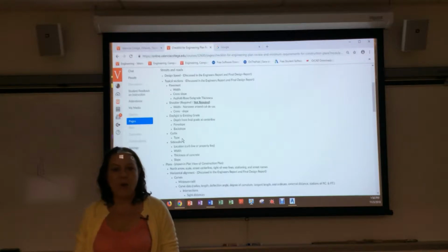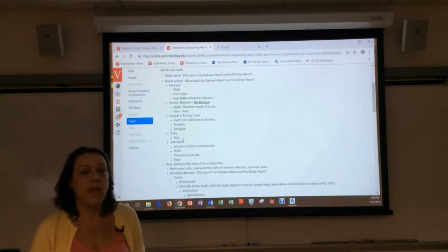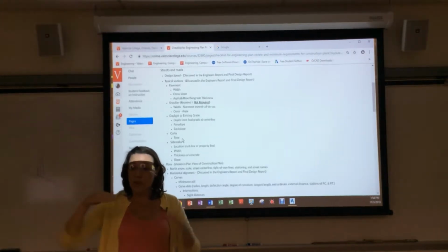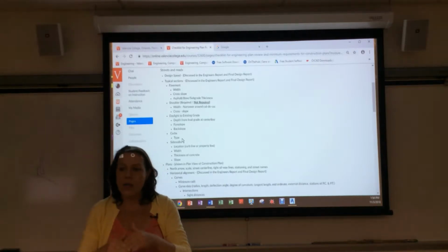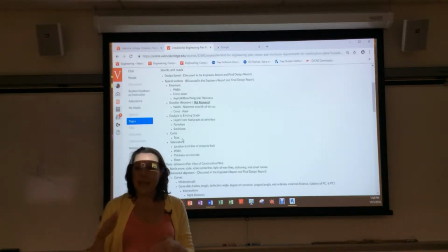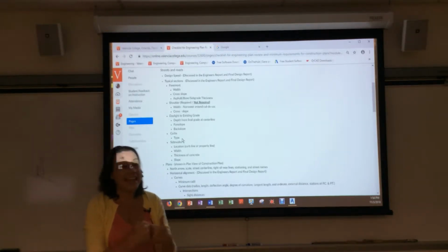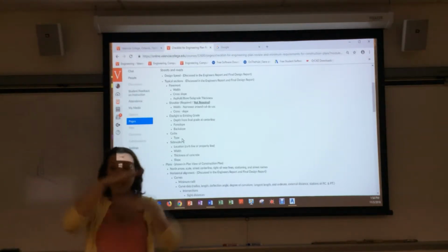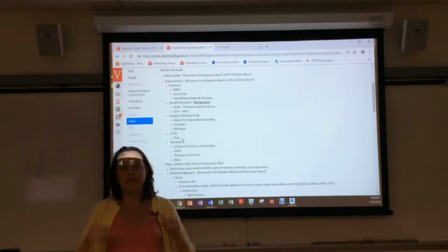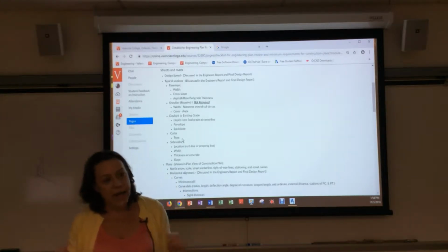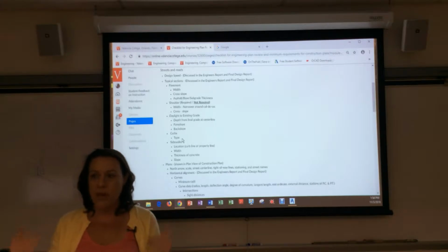Okay, they can't go over 2%. The other thing is when you're going longitudinally on a sidewalk, you can't go over 2% unless it's a short distance. And then you have to fit ADA code. It goes up a bit and it has a flat ramp because anybody in a wheelchair has to be able to get from point A to B without having any issue.